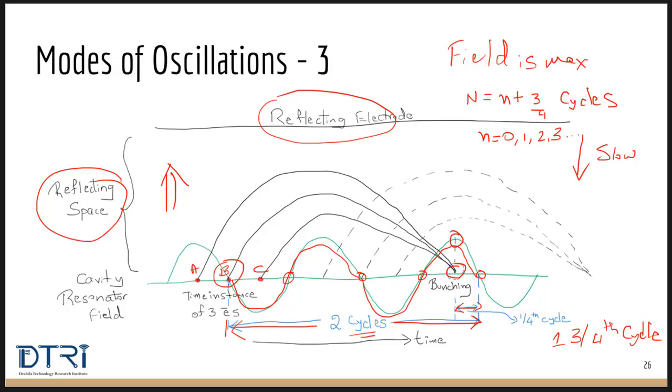Based on these three major parameters, which are the mechanical design of the cavity, reflector voltage, and acceleration voltage, bunching happens. So let me repeat. Based on the three major parameters, which are the mechanical design of the cavity, reflector voltage and the acceleration voltage, bunching happens.